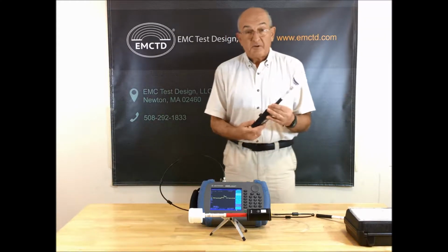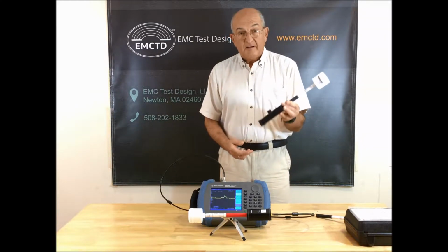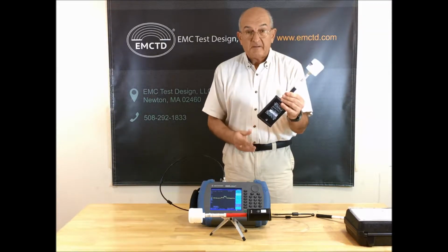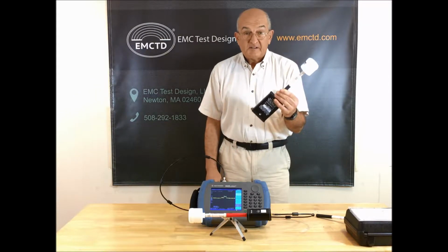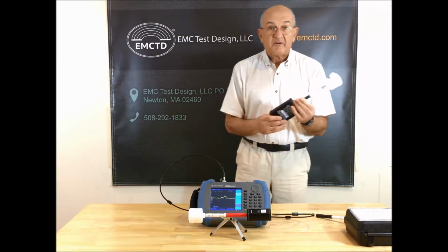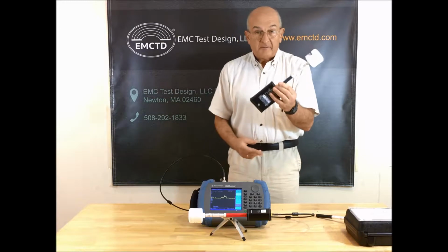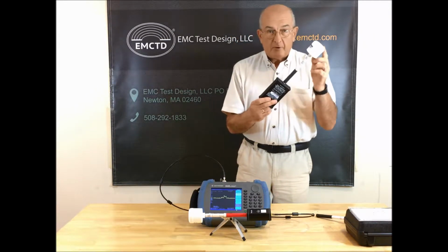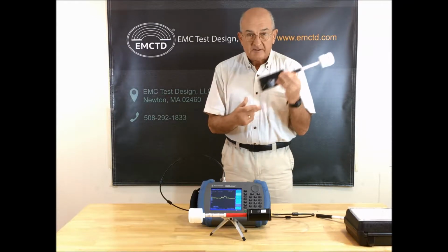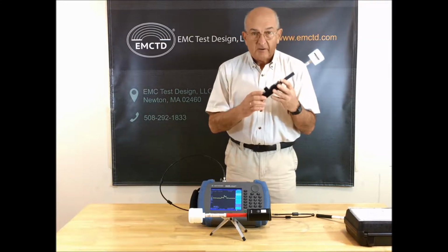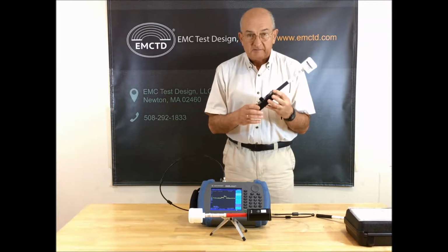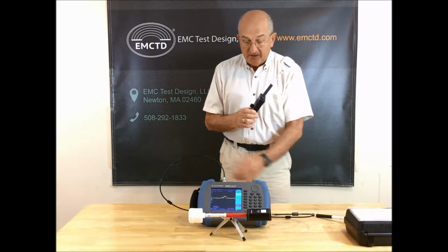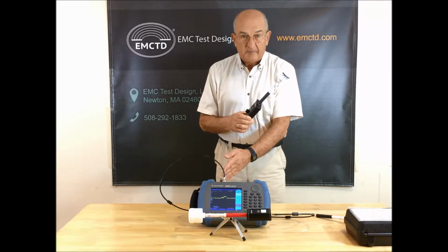Isotropic antenna actually looks very similar to our other very popular product, probe. This in my hand is Broadband probe that has the same frequency range, almost same frequency range as this antenna. Nevertheless, this is a different device. Output of the probe is DC signal that requires DC voltmeter to be amplified, corrected, and displayed. Output of the isotropic antenna is RF signal that you need to use with spectrum analyzer.